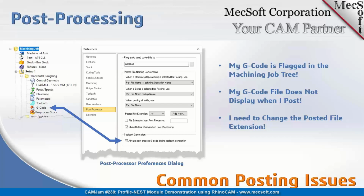We introduced a new icon called G-code. If you look at the CAM preferences here in the middle dialog, there's a checkbox called Always Post-Process G-code during toolpath generation. What that means is when you generate the operation, you can have your G-code generate automatically, and it'll be saved with the file.